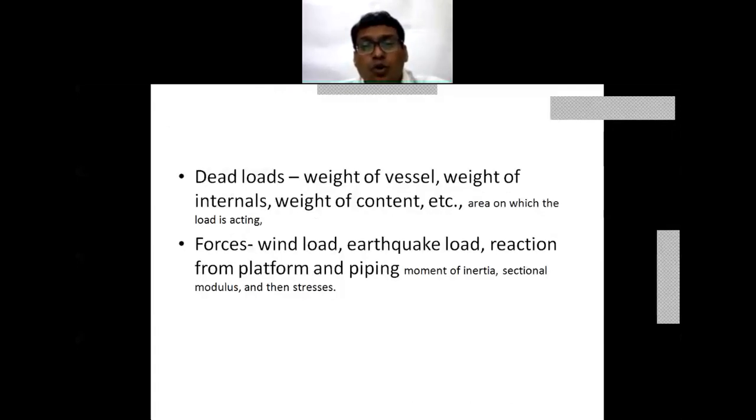Then the dead load, we are calling the dead load. Sometimes the terminologies may be different. That is the weight of the vessel plus weight of the internals plus the weight of the contents. Area on which the load is acting is taken into consideration. Then the forces, that is wind load, earthquake, then reactions from the platform or from the supports, that is also there.